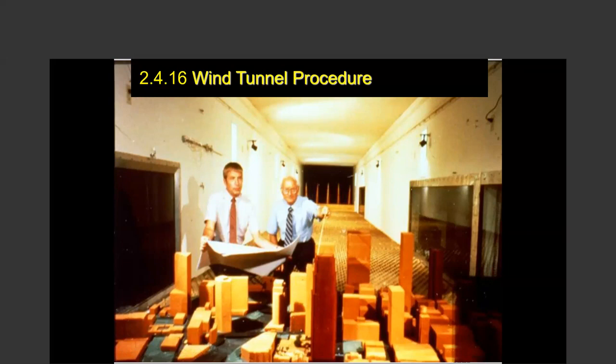Your building will be made of a different material, heavily instrumented. All the neighboring buildings will be to proper scale, but they are of inferior material, cheaper material, and not instrumented. Okay. The carpet simulates the roughness of the terrain, and you can change the wind velocity, and by rotating the models you can change the wind direction. Okay, this whole thing will be on a table or something that is possible to rotate.